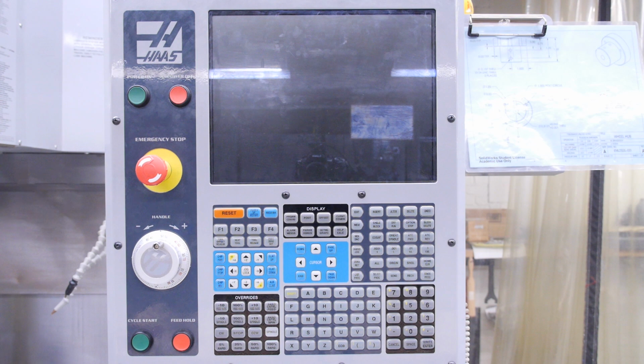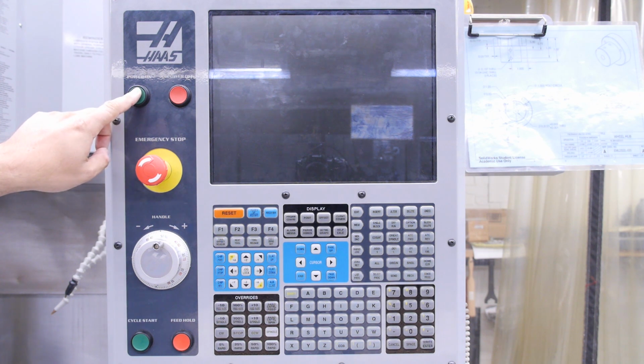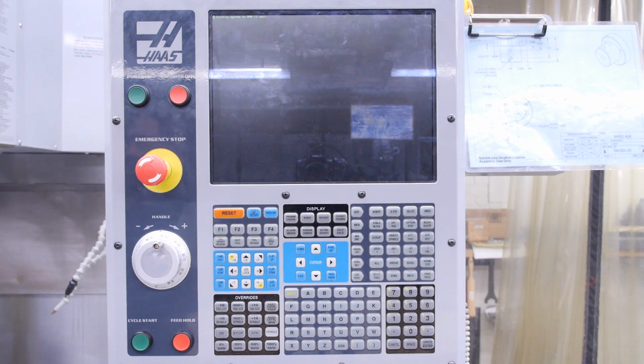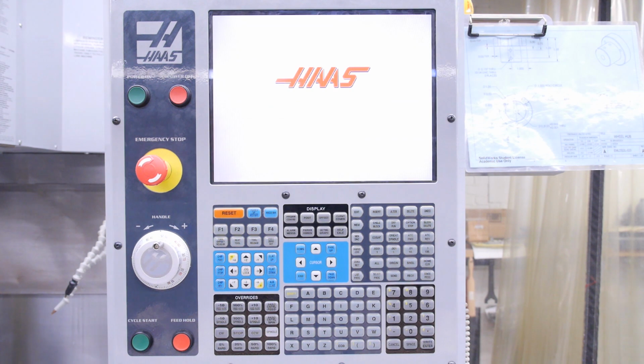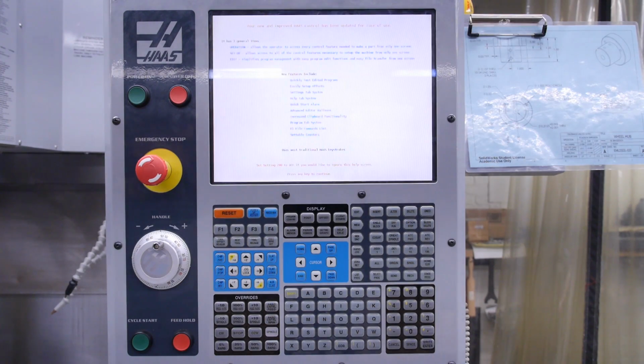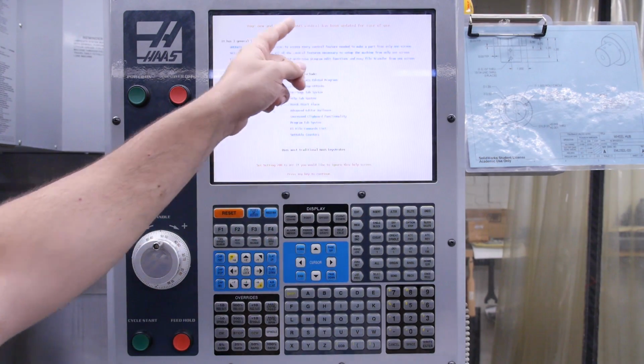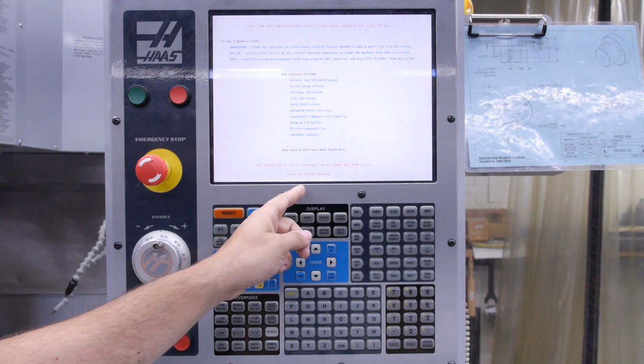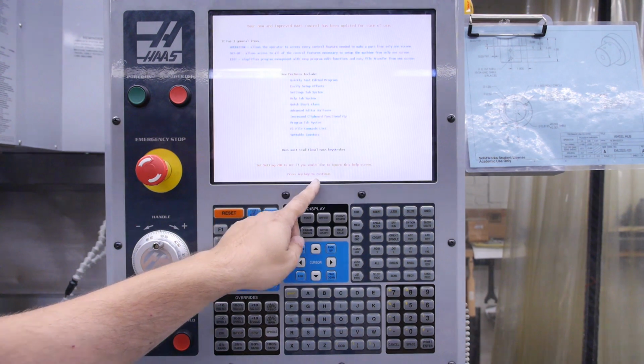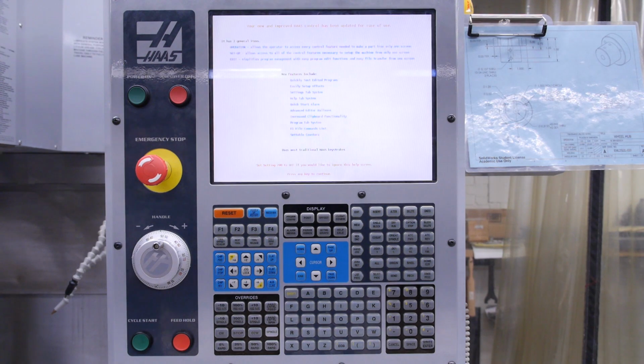Next, we turn the machine on. As noted on the TA outline, students don't have to see this part. You can do it a few minutes before each lab begins or while the students are cleaning up their lathe. The first step is to press the green power on button located at the top left-hand corner of the machine console. As noted on the TA outline, it typically takes about 60 seconds for the CNC's computer to boot. Once booted, we are greeted by the machine's initialization screen or introduction screen, at the bottom of which we are directed to press any key to continue.